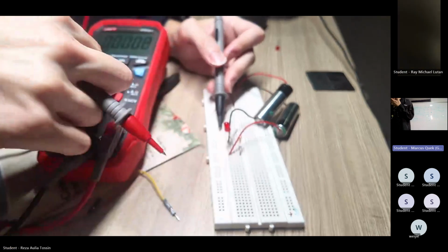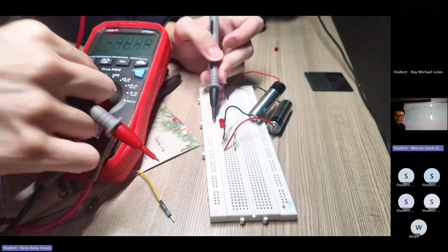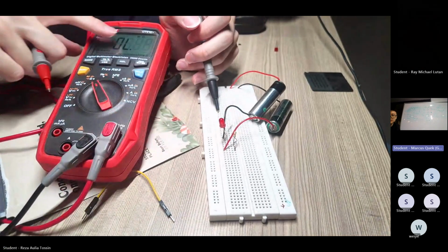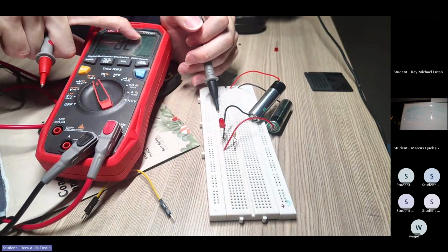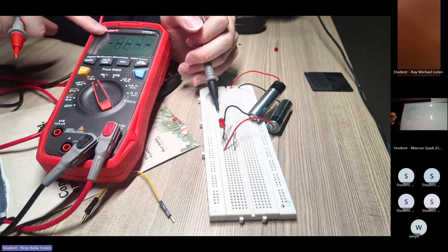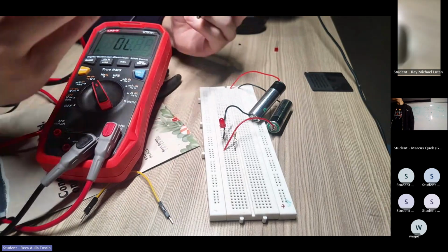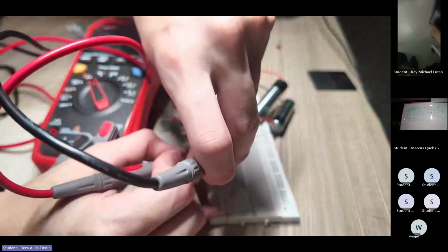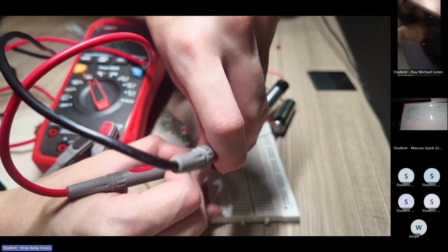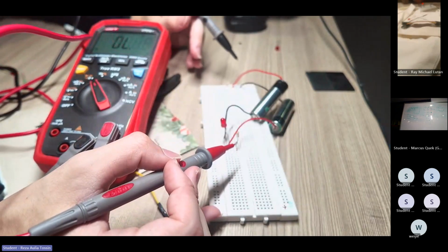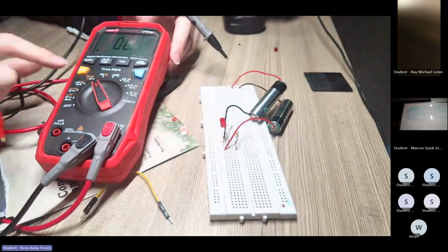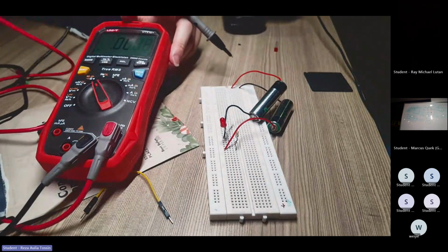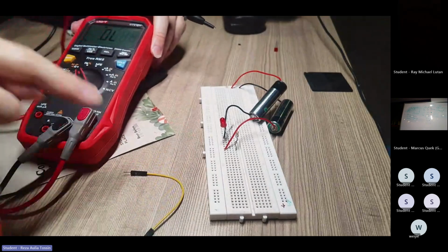I can switch to resistance mode like this. See the ohm symbol, this means that I'm in resistance mode. If I press select, then I can detect different things. This is continuity. It says, is there a short circuit or not? For example, I can touch the same leg of the resistor. Now I know my resistor is not broken. This is more useful for wires, like this jumper. Can I trust this jumper? You check continuity across it.